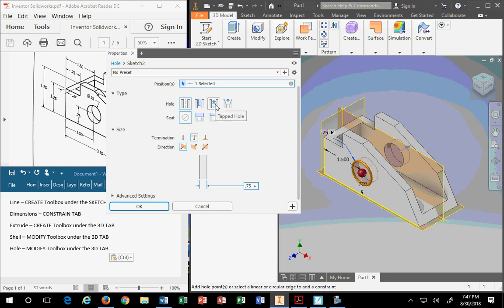The next one is a tapped hole, which is literally an internal thread, which we call a female thread, or a B thread, an inside thread. You want that if you want it to actually hold the fastener instead of getting a nut. And the last one is a tapered thread, which we use in the plumbing industry when you're trying to create a tight seal, a seal type thread. So anything related to plumbing and gas will use that type of thread type.